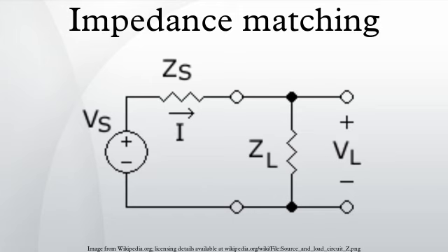Impedance matching is not always necessary. For example, if a source with a low impedance is connected to a load with a high impedance, the power that can pass through the connection is limited by the higher impedance. This maximum voltage connection is a common configuration called impedance bridging or voltage bridging, and is widely used in signal processing. In such applications, delivering a high voltage is often more important than maximum power transfer.